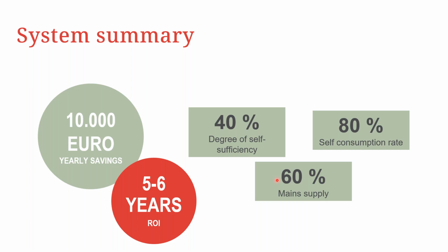So in a nutshell, you have done the installation, you had some theoretical expectations as far as the savings and the energy generation of the PV system is concerned, but you have to proactively do data analysis in Fronius SolarWeb to be able to advise your customers on a frequent basis, maybe every 6 months or every 12 months, depending on what you feel is convenient.